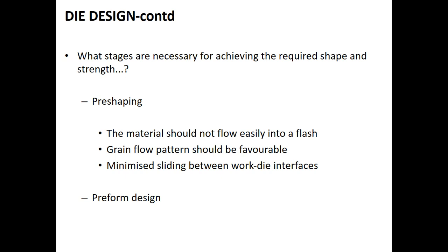So in a properly pre-shaped workpiece, the material should not flow easily into flash, otherwise the die filling will be incomplete.